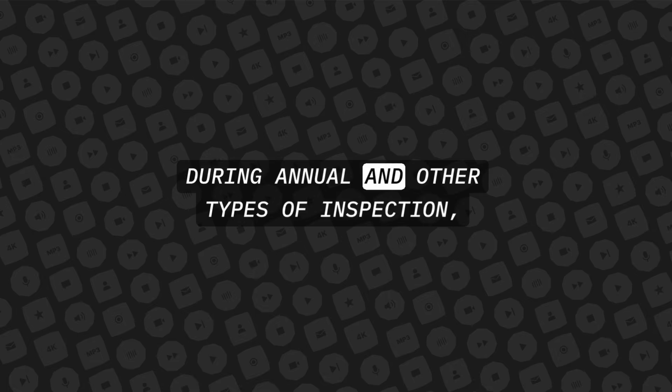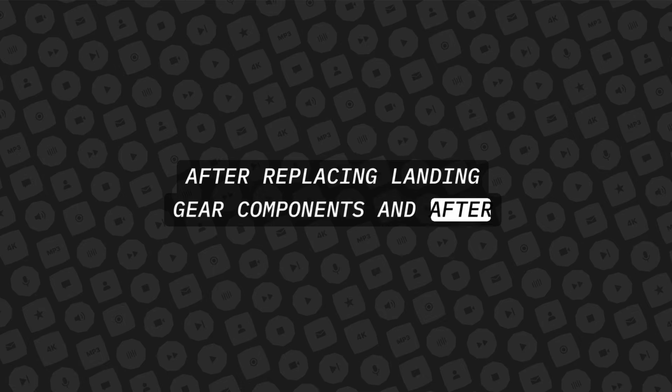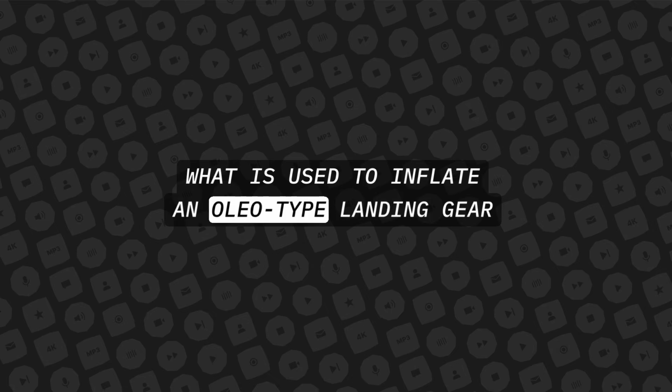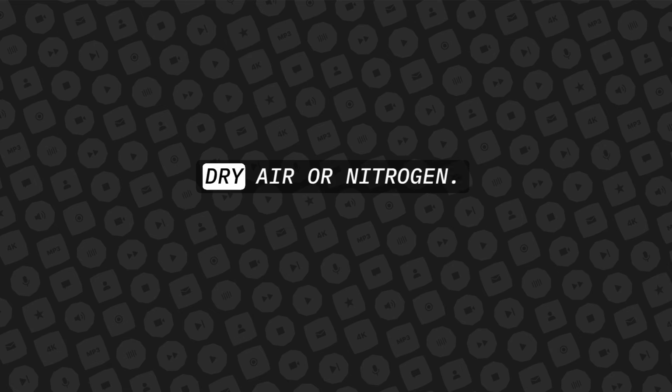During annual and other types of inspection, after replacing landing gear components, and after any hard landing. What is used to inflate an oleo-type landing gear shock strut? Inflate the strut with a high-pressure source of dry air or nitrogen. Where would you look to find proper tire inflation information?